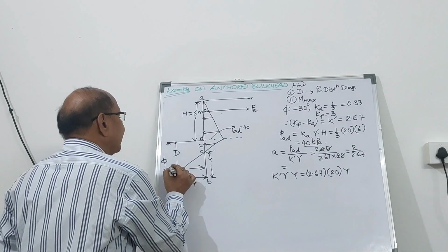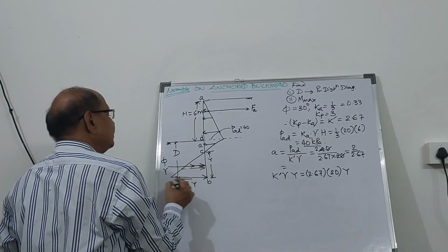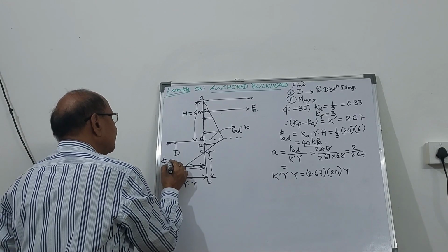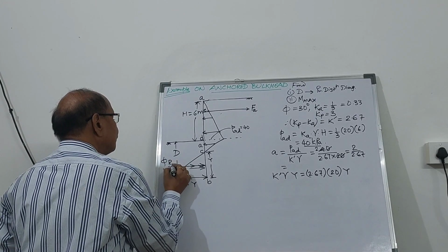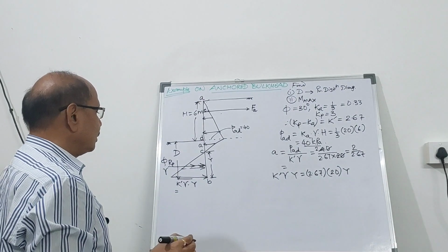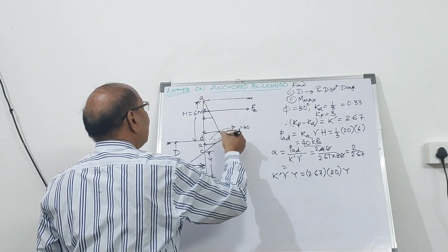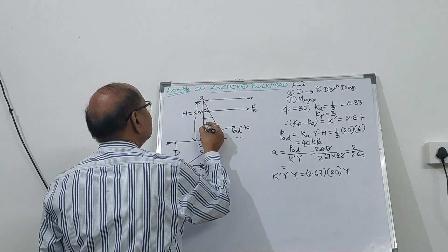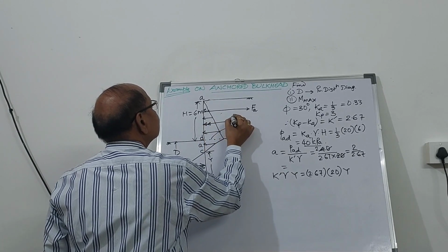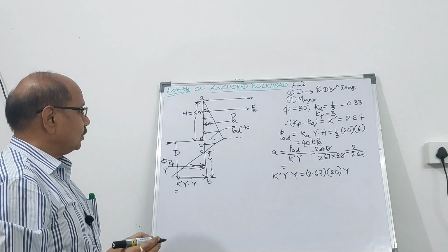Therefore, you can find out the resultant of this pressure distribution diagram that will be giving you the resultant passive thrust or passive resistance RP. And the area of the active earth pressure distribution diagram will give you, this resultant will be the active thrust PA.